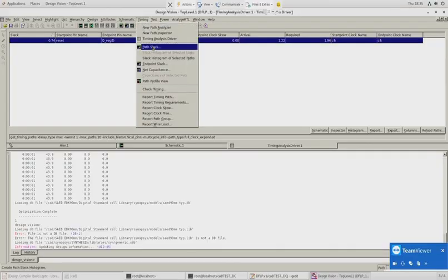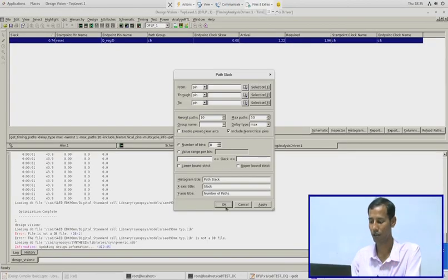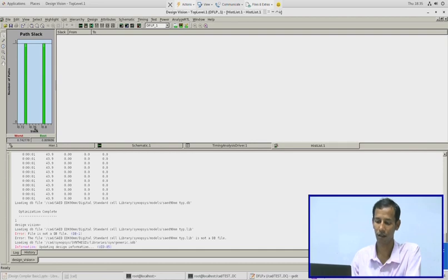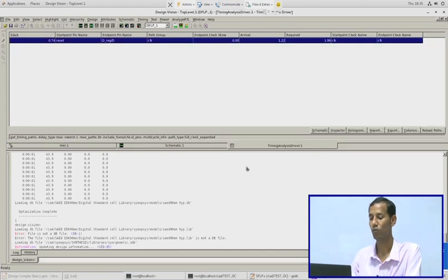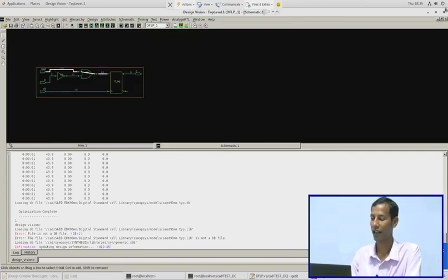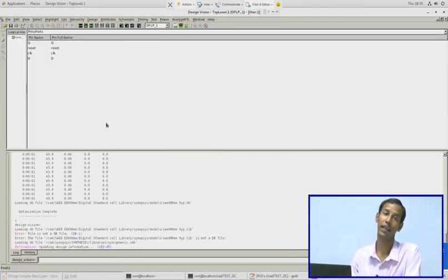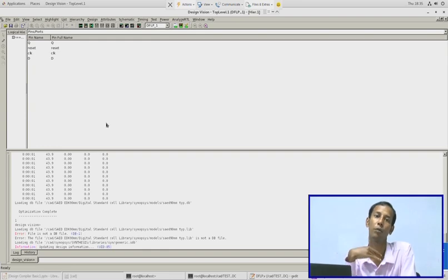So what is the slack? If I click on this, what is the path slack? It will show me the corresponding path slack, and the slack value is 0.742778. That means the clock period I set, 2 nanosecond, is more than needed, so I can reduce the clock period again, let's consider 0.8.